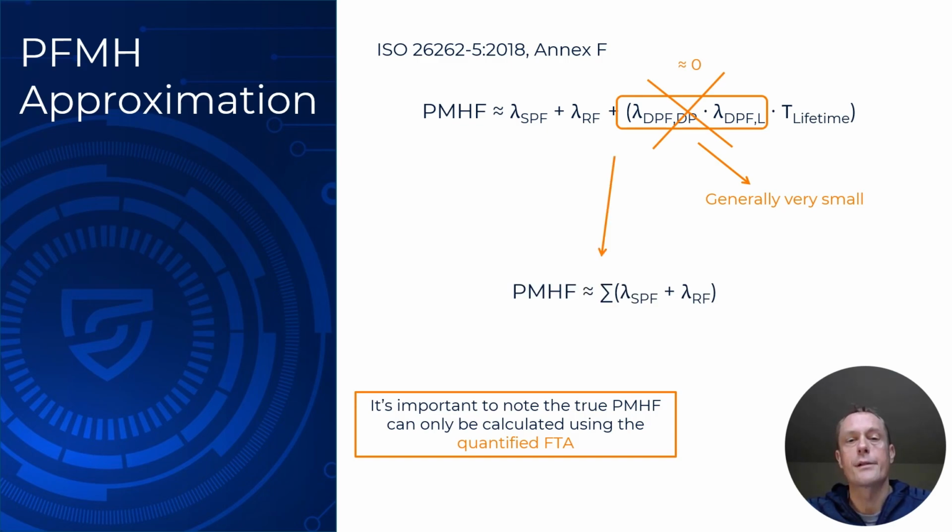When we do that, then this expression boils down to just the summation of the single point fault plus the residual fault. Now, I do want to note, it's very important, that the only true calculation of PMHF is through the quantified fault tree. So this is for support with the FMEDA.